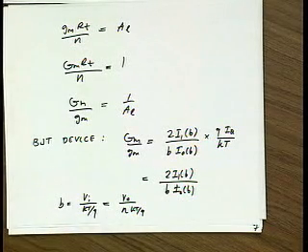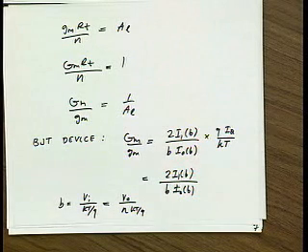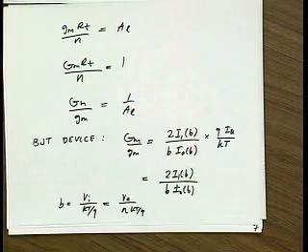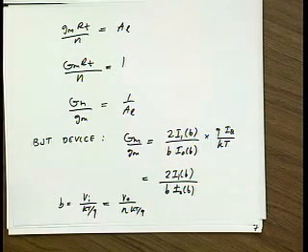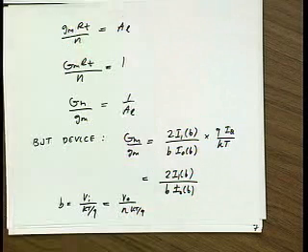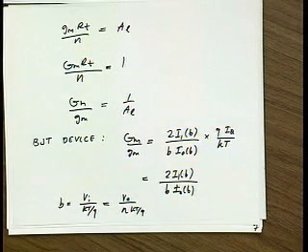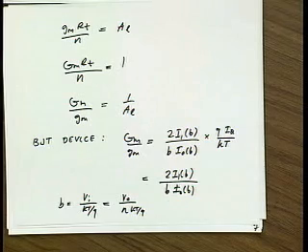So now you guys have the recipe to go home and design a BJT-based oscillator, because these functions are well known. For any other kind of oscillator, all you have to do is generate one curve, which is a large signal GM versus the oscillation amplitude, and you have the recipe essentially for determining what the output amplitude is going to be. Okay? Question? Yeah, I don't see how you simplify and then get rid of the Q over KT.